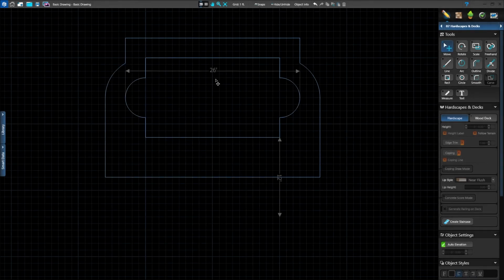The next tool gives us the ability to add text to our design in both 2D and 3D. Activate the Text tool and left-click in the 2D grid to create a text block. We'll use the keyboard to enter text. When we enter text in 2D, it will appear on our 2D plan. When we enter text in 3D, it will appear in our 3D presentation.